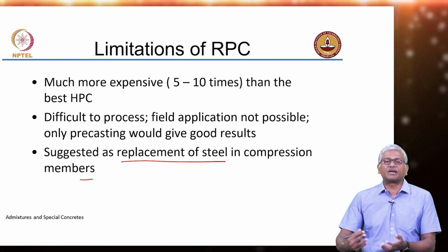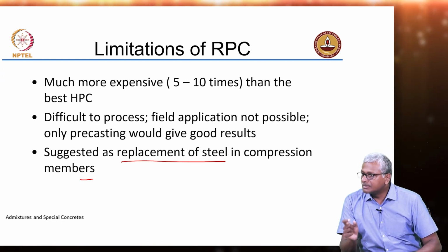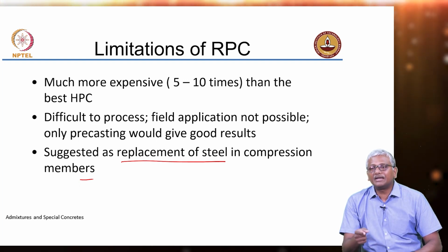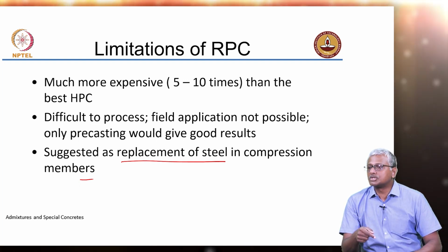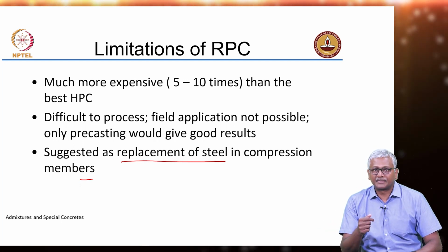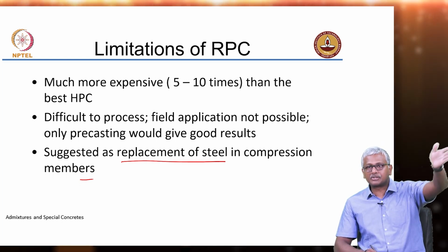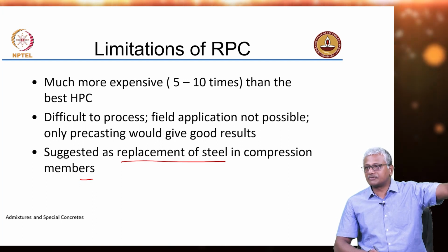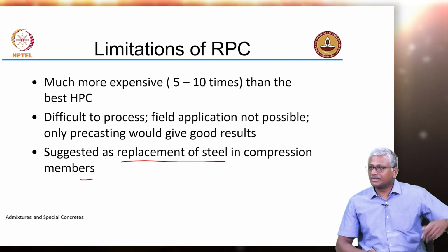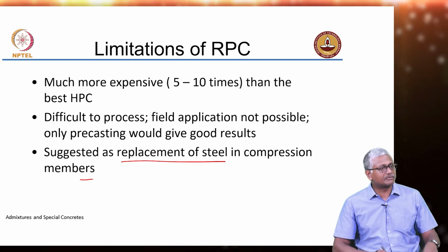If you have exposed steel fiber, they can corrode, but mostly what happens is the steel that is used for these fibers, the high strength steel fibers, they have much lesser corrosion potential as compared to your mild steel that is used for reinforcement. So if you go on our road that goes from Mandakini Hostel to the research park, the slabs are all with fiber reinforced concrete. In fact, you can actually see some steel fibers on the top surface. They are not corroding. There is no corrosion there. So it depends on the material of the steel fiber.